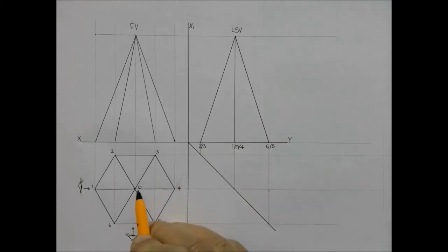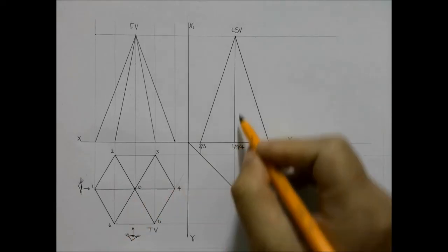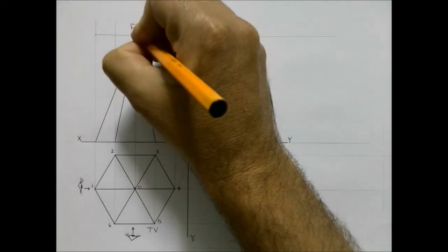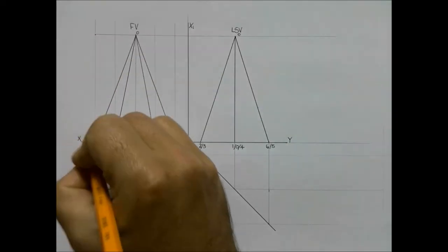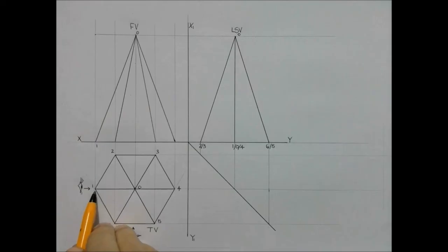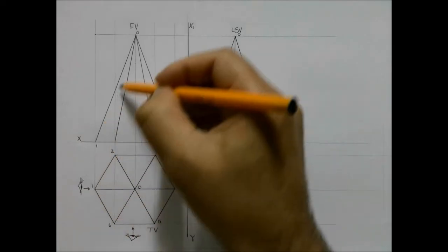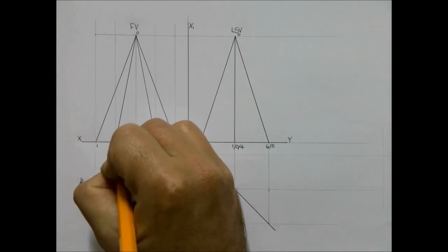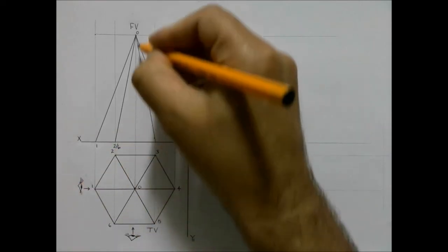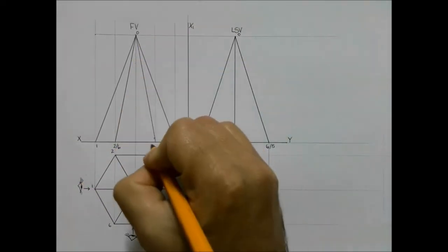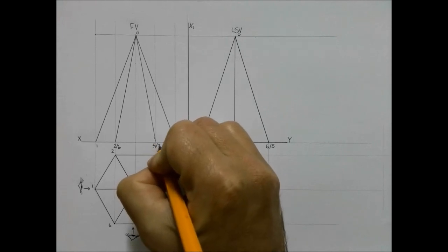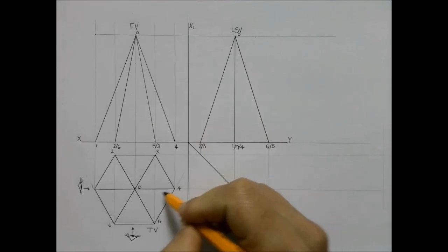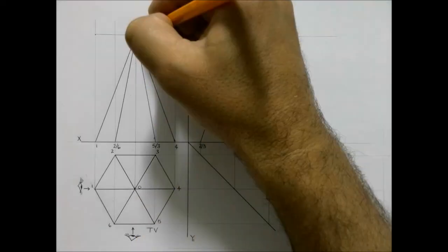And we know that the 0 is obviously the apex, so I'm going to be taking that 0 up to the top. I'm going to do the same over there. 1 projected up will be there, so that line there from 1 to 0 will be from 1 to 0. Then we'll have 2 and 6. You'll have your line 0 going up. You'll have 5 and 3 in line. You'll have number 4. So from 4 to 0 will be from 4 to 0.